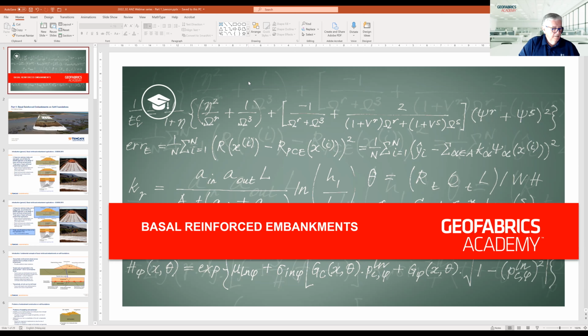Yeah. What happens is when you come to do those calculations, you do the calculation for the ultimate limit state, which is the maximum load. And then from that, you calculate what the initial strength of the reinforcement should be. Then you do a second calculation for serviceability state. So you do two sets of calculations.